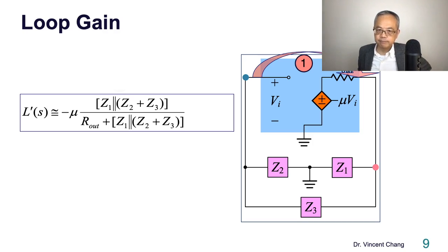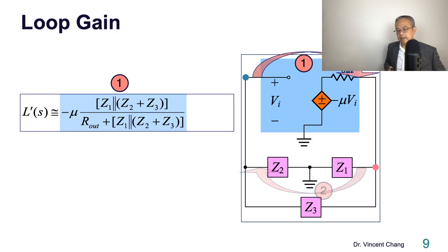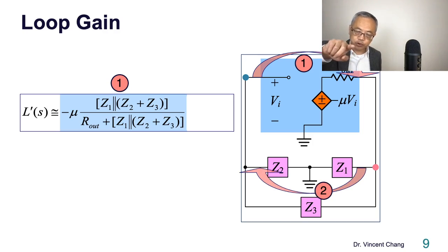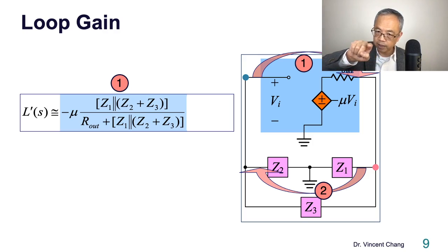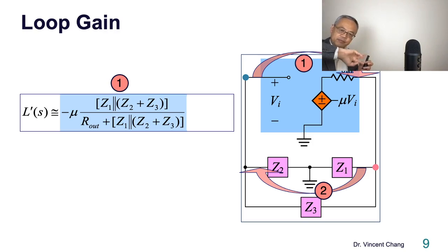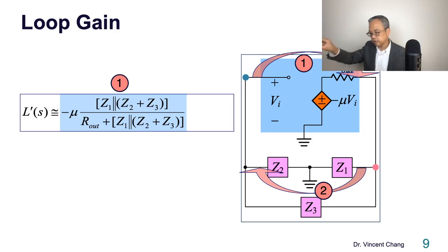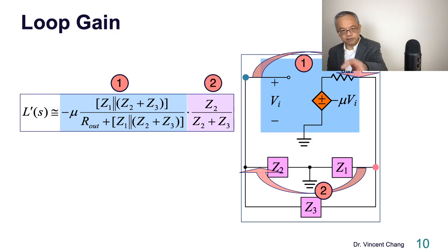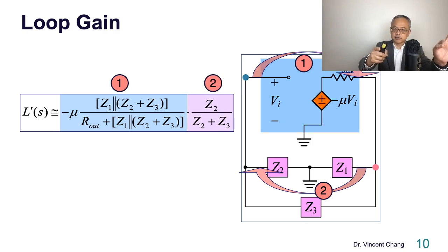The first factor. And now it's the second factor. The second factor is easier. For the second factor, we try to find the aqua voltage divided by the pink voltage through the so-called frequency selective network. So it's going to be what? A divider. So the denominator is going to be, take notes, R2 plus R2 plus 3. So what's the numerator? 2, right? Like this. So this is factor 2. It's very easy, just a divider.